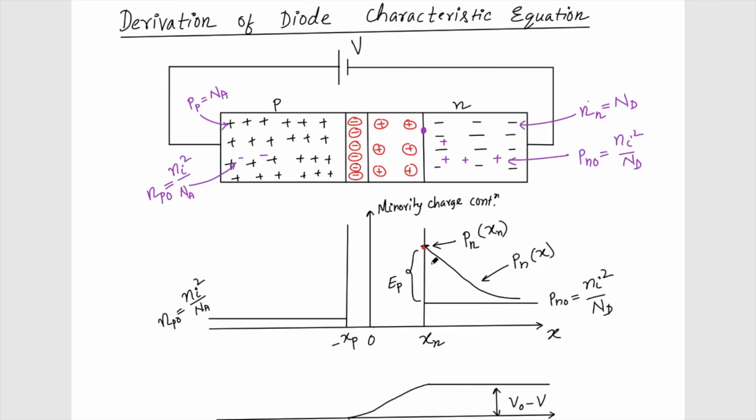Similar to the diffusion of the holes on this side, there will be diffusion of the electrons on the other side, from here to here, and I am going to get a similar curve, which I can call the electrons, n on the p side, np. I can do a similar derivation for the electrons, and I will get a similar current density, which is maximum here, and this is only the diffusion current. So again I can write the current density of the diffusion current here.